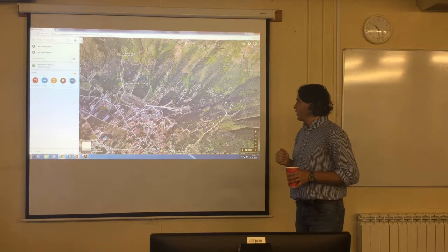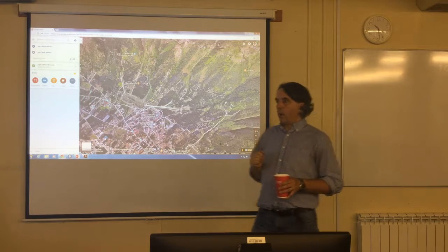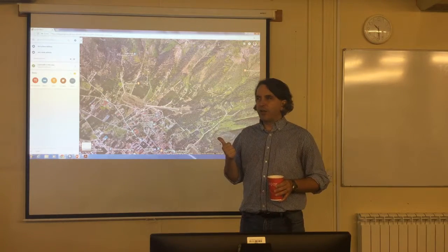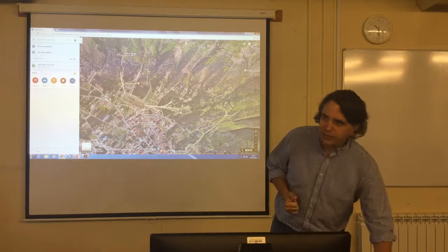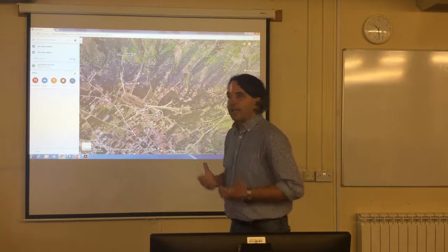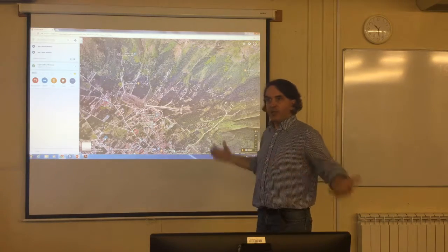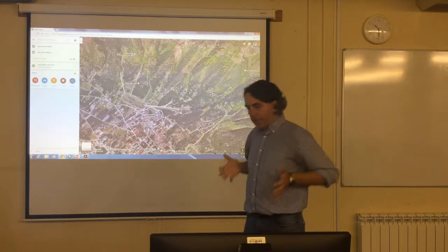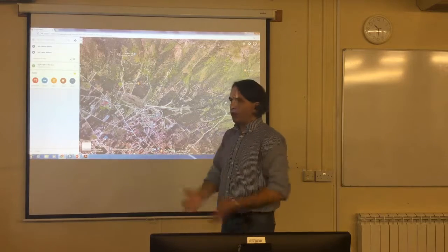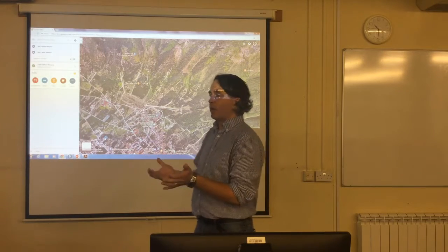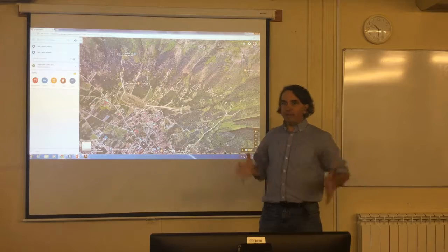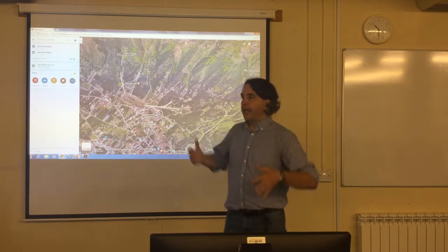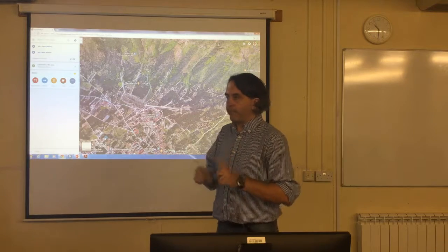Okay. So why would you concrete a channel with debris flow? What does debris flow do? Debris flows are very interesting processes. They what's termed bulk. So as they come down a slope, they entrain other material. Okay, and they get bigger as they come down the slope. As they're coming down, they're eroding, more material is coming in, and they get bigger and bigger and bigger. Okay? So if I concrete a channel, can my debris flow now bulk anymore? No, it can't. Can it? It can't pick up any more new material, which is a good thing.